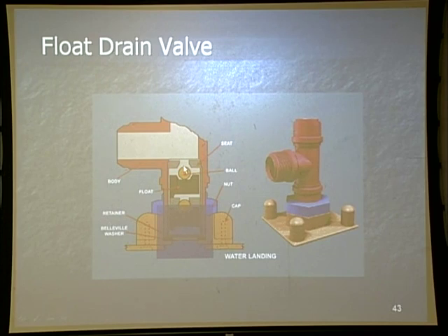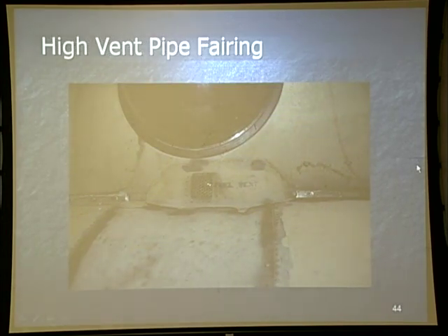So we have a secondary vent system on the top of the aircraft, and it looks just like that. Under this fiberglass cover is your actual vent. Just like a snorkel, it's going to take over if the primary vent, which is the bottom, is sealed or blocked.